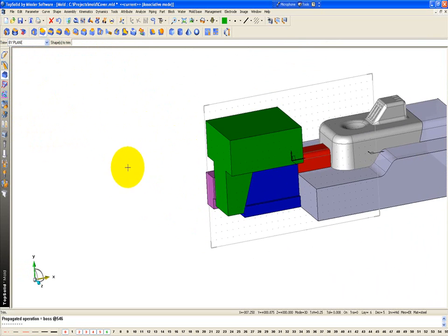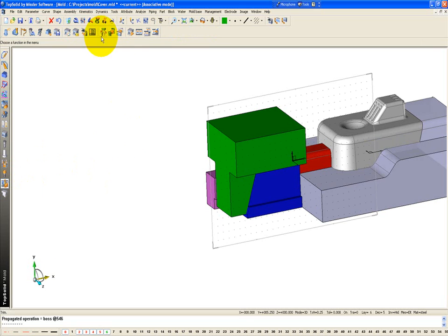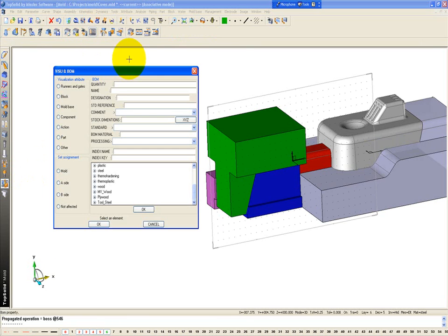Now the last thing we need to do is add this to mold visualization. So I'm going to go back to Management, back to my BOM property editor, select this, and call this Backlock. Maybe for my designation, which of course means description, this is my custom backlock. Or again, you can just call it backlock, whatever. You can get your stock dimensions if you want. Select the button, select your coordinate system. Now you know how big of a piece of steel you need to order.